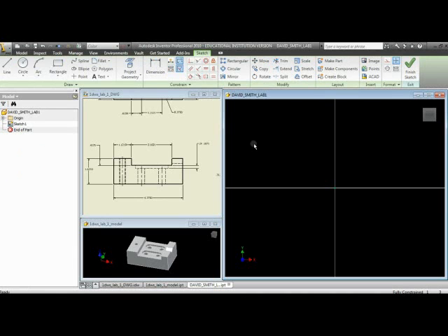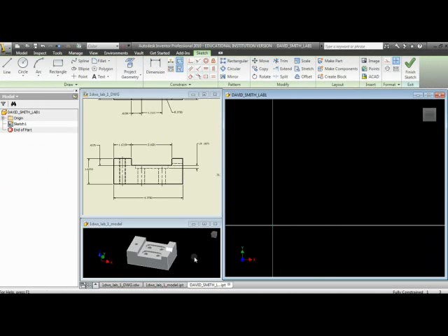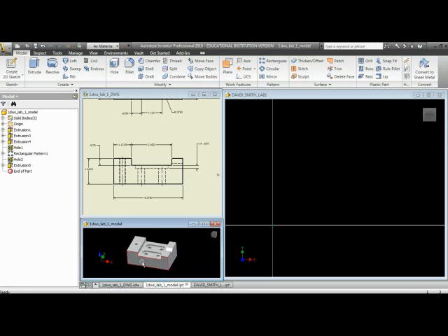Now, the only problem with naming that first is once we did that, we got out of our first original sketch. So to get back into that, I'm going to right click and hit Edit Sketch. One thing I will caution you about is I'm not a big fan of having extra sketches that are not being used. So don't start a new sketch there. Just right click on that sketch and hit Edit Sketch.